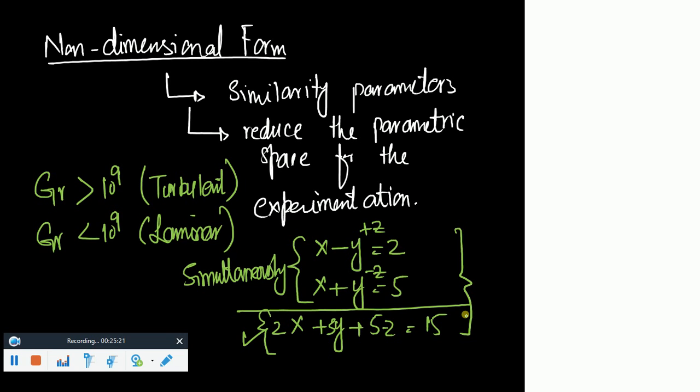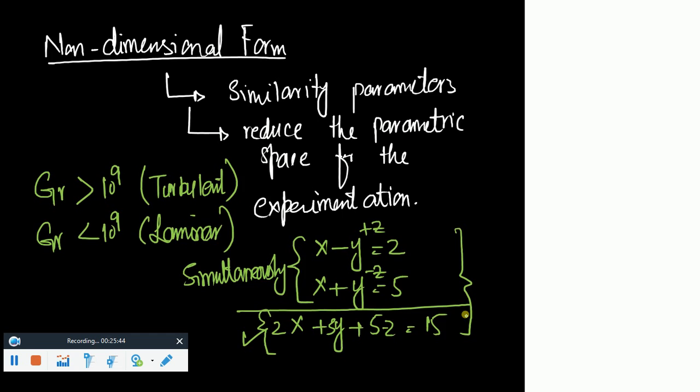And if you check the box, it would solve the energy equation for you after it solves the continuity and momentum equations. So this is the reason behind it, right? Now my point is, why are you... yes, reference velocity.